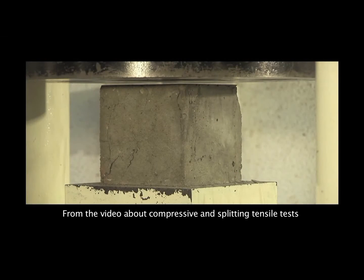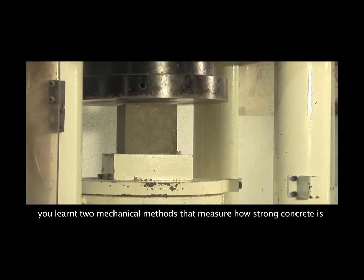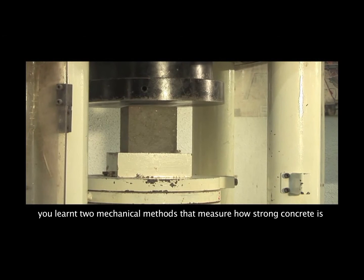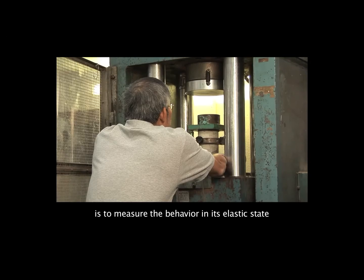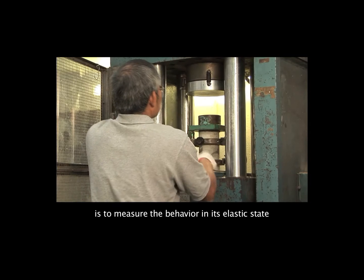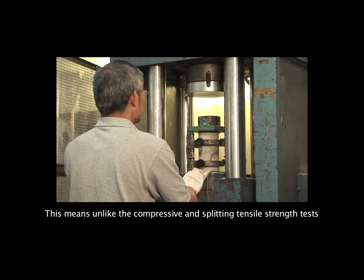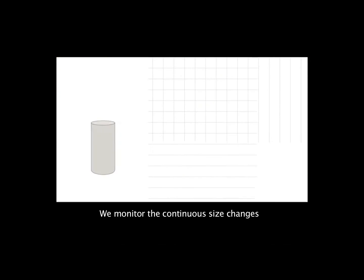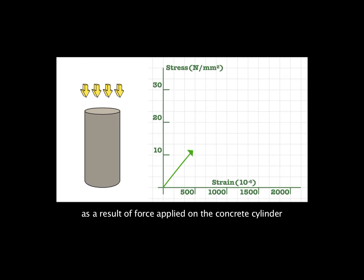From the video about compressive and splitting tensile strength tests, you learnt two mechanical methods that measure how strong concrete is. Another way to understand the mechanical property of concrete more closely is to measure the behavior in its elastic state. This means, unlike the compressive and splitting tensile strength tests, we monitor the continuous size changes as a result of force applied on the concrete cylinder.